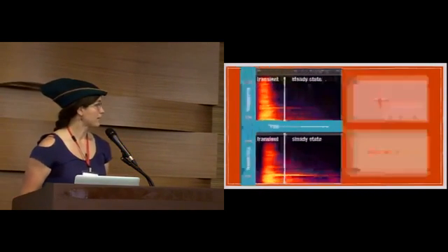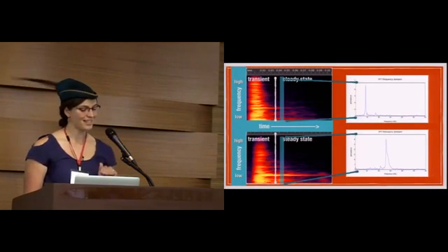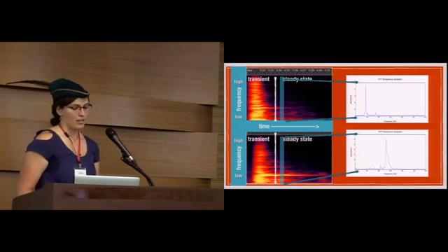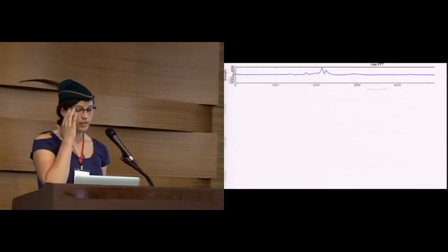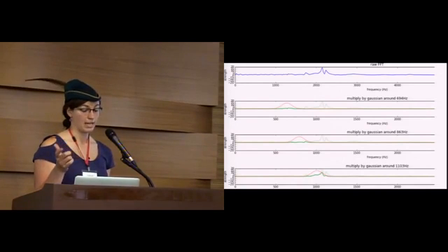Our algorithm looks at a slice of the steady state and uses an FFT to pull out the most prominent frequencies. This classification takes about 100 milliseconds from transient to final output. Starting at the raw FFT, we can then look in the region of all the predicted frequencies to see where there's the most energy. So for this we use multiplication by Gaussians.